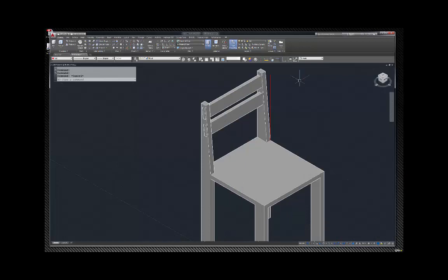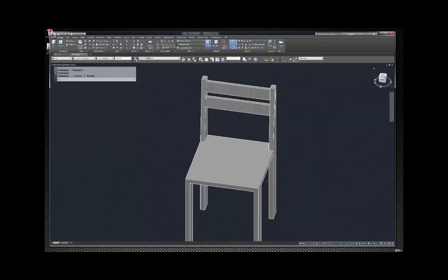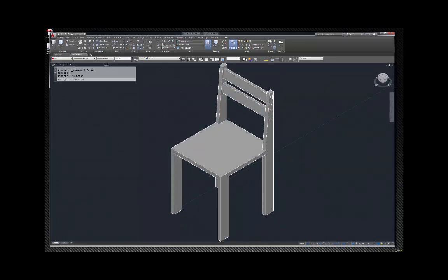Okay. And then we can just go over here to, I'm going to delete that red line, which is our little polyline that we had. And I'm going to go in here, I'm going to go pick union. You have to pick union first before you grab the objects. And then grab everything and then hit enter, and then it becomes a single entity. Okay.